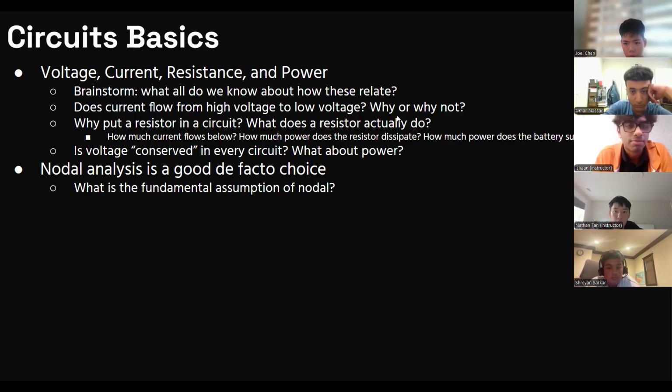You say charge conservation. How does charge conservation apply to KCL? So when you have a charge, say 1 amp, when it splits into two different paths, like a parallel circuit, the total charge will remain the same if you add up all the charges, negative and positive. Yeah. So what you're really saying, I'll rephrase it, is all the current that goes in has to equal all the current that goes out. Yeah. Because current is just charge flowing per unit time. We just talked about power being energy per unit time. Current is charge per unit time. So you said the right thing. But it's per unit time that we're really talking about for current.